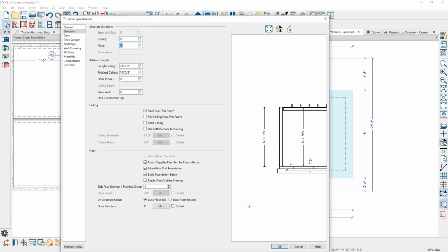No, wait, you've already defined I want the existing finished floor to be the same elevation as the new finished floor, and now you're changing it. Right. So I would raise, because the existing condition is your floor joists that are already in the field, sitting on the stem wall. So that's going to raise that floor up, give it a number, 15 inches or something, right? Okay. On the left side. So on the right side, I need to raise this floor up that same amount.